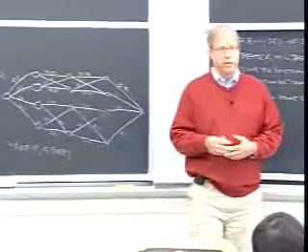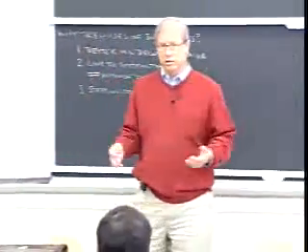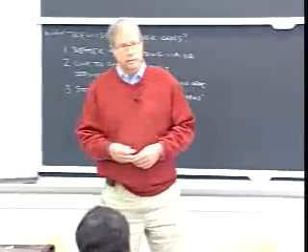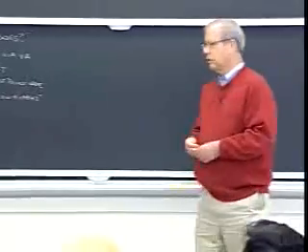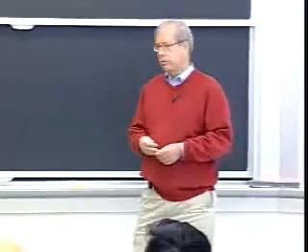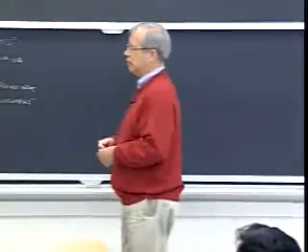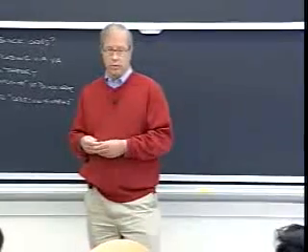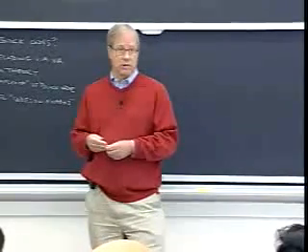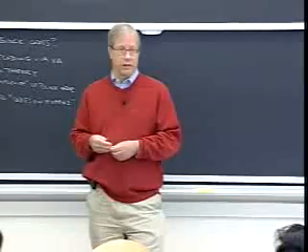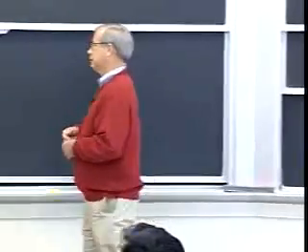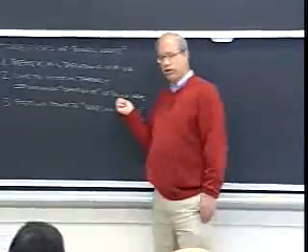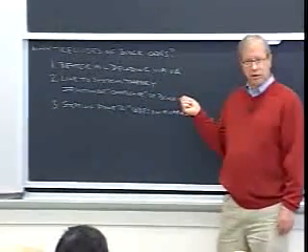Well, now we have a little bit of a handle on it. We can say its complexity is that of a 4-state machine. So trellis complexity gives us a measure of the complexity of a block code, so that we can, for instance, say that Reed-Muller codes tend to be less complex than BCH codes. I'll try to give some substance to that as we go along. So we get additional parameters that have more to do with what we really care about, which is decoding complexity.